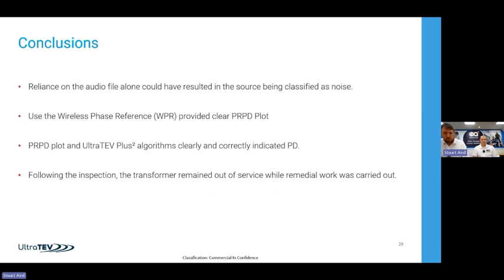So conclusions from that one: reliance on the audio file alone, you could have overlooked it. You would have heard there's some activity there, but you may have just put that down to noise. Don't let it detract from the fact you should always use a headphone. You should always be listening for this, because the fact there's a difference in the first place is why you look deeper. So that's quite important. But then once you pause, you let that plot build up, you use the phase reference, we'll then be able to give it a good classification and act upon the output of that.